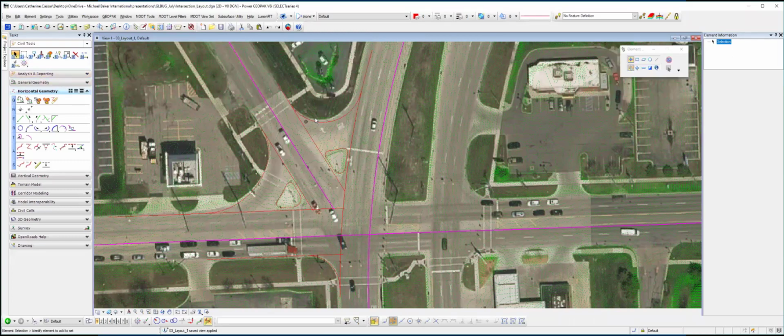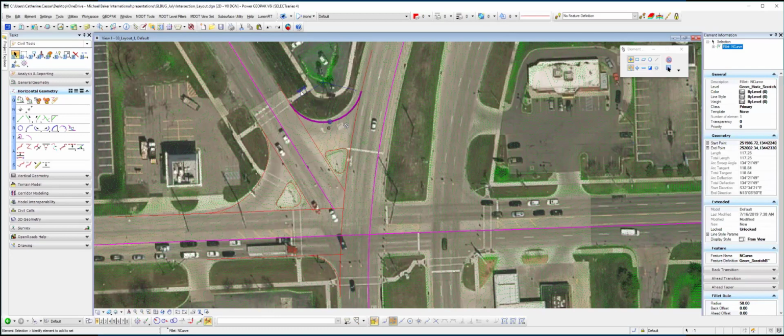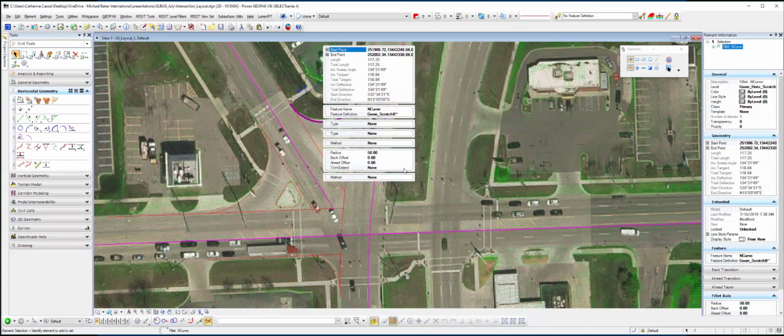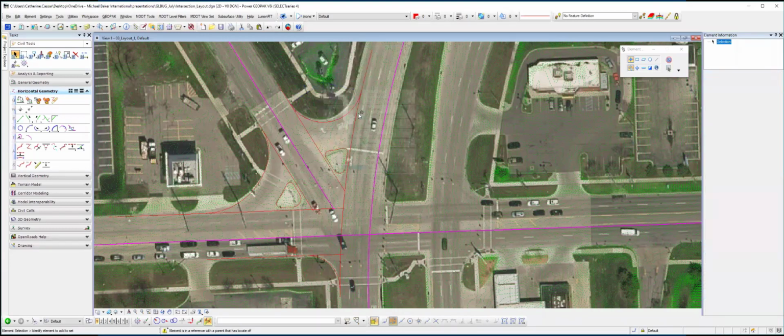So we're going to get into the layout of the radii. In this case, this is just a regular arc between, and you'll notice I'm not allowing this arc to clip anything. So my trim extend is currently at none. The reason is I don't want to make intervals of my through baselines. If these become intervals, sometimes it's challenging to get intervals to accept or to send vertical information to another element. So I typically don't want my baselines at all to be intervals. I want them to be something else. I noticed that this one is an interval in this file, that I changed it in the vertical file because it was causing problems. So you typically don't want anything here to be an interval.